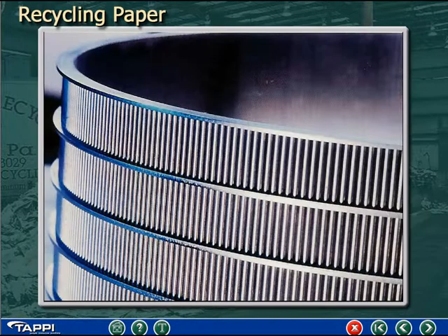Fine slotted screens are perhaps the most important step in any OCC system making high-quality stock for linerboard production where sheet appearance is of primary importance. Screening out contaminants with fine slots is the best method for controlling stickies, a major problem in most OCC processing plants, so a lot of attention needs to be paid to this step in the process. Doing so will result in much better pulp quality and lower overall costs of the operation.